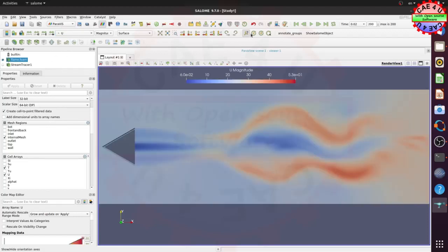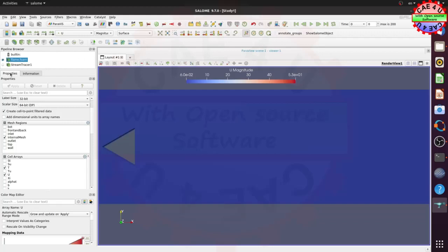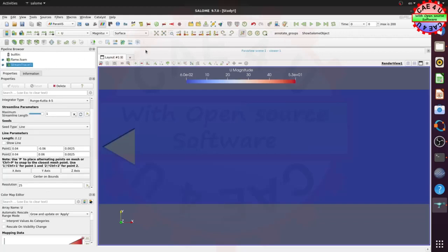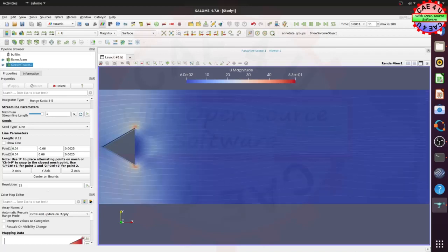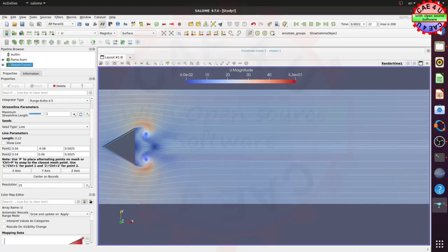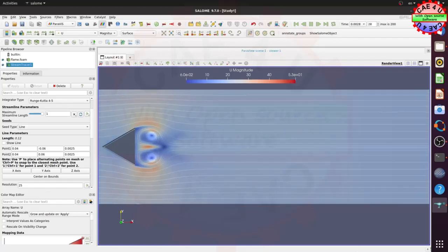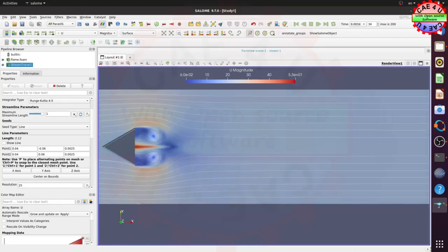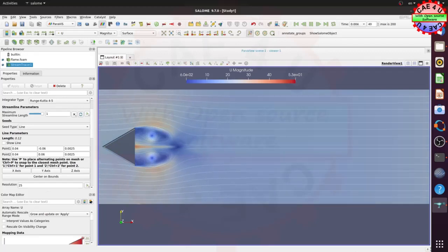It is also interesting to see the flow field around the bluff body. So we have superimposed streamlines over the velocity magnitude plot. The recirculation zone behind the flame holder holds the flame. Even a weaker ignition source could initiate the combustion.